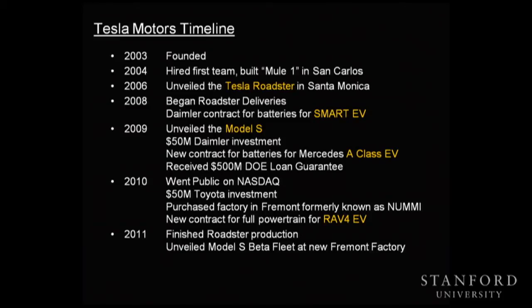You think about stamping a body panel, like big sheet metal panels. How are you going to build a prototype of one of those? And yet they do. There are companies, of course, in the Detroit area that specialize in doing this kind of stuff. And just as an aside, that particular technology is they take some alloy of zinc and tin and aluminum or something, it's called Kirksite. And it's a fairly low melting temperature, very kind of brittle and stiff. But because it's such a low melting temperature, it's easy to recover. So they pour out, and it has very low shrink rate. So they can pour huge blocks of this stuff, machine a shape into it, stamp out a few hundred body panels, and then melt it down and all the shavings that went with it and start over again. So you actually can stamp out these big pieces of stuff.